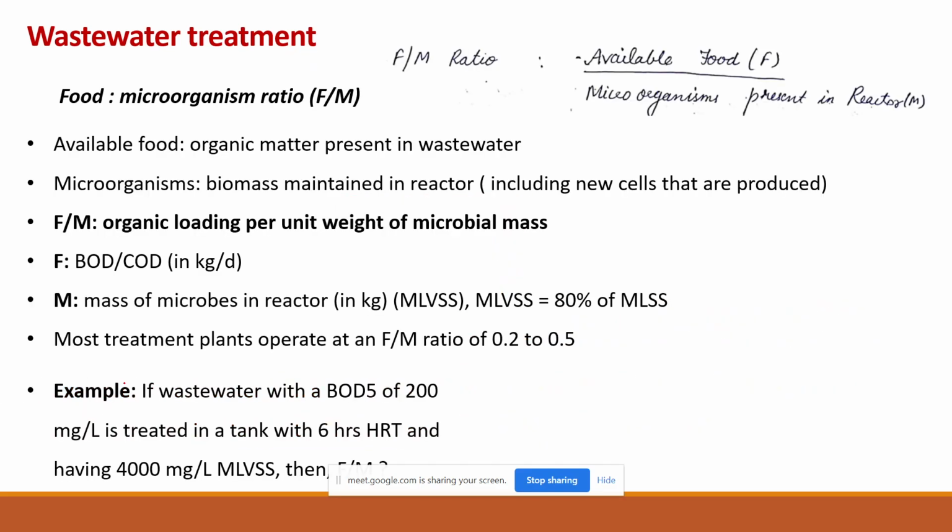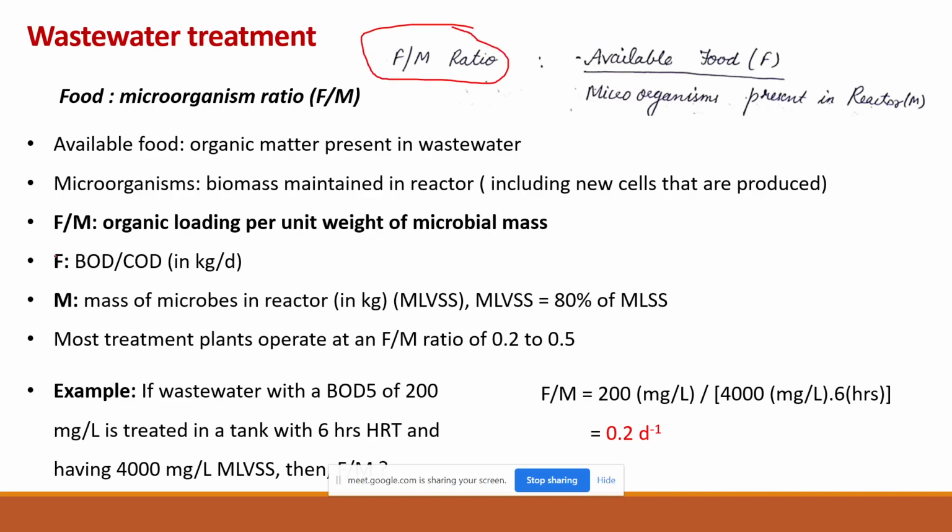After hydraulic retention time, we studied the F by M ratio, which is important so that the appropriate treatment takes place. Then we again did two numericals in this part. Your F by M ratio is basically BOD or COD in kg per day divided by MLVSS in kg, right? So we were provided with the BOD, HRT and MLVSS. Through these data, we obtained an F by M ratio of 0.2 day inverse.